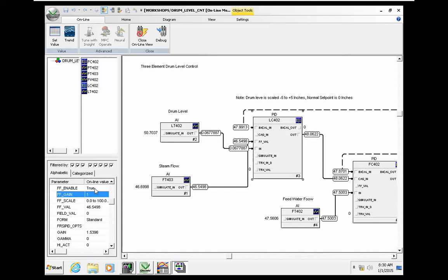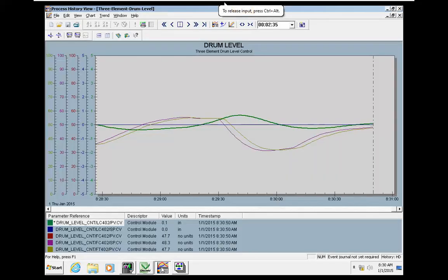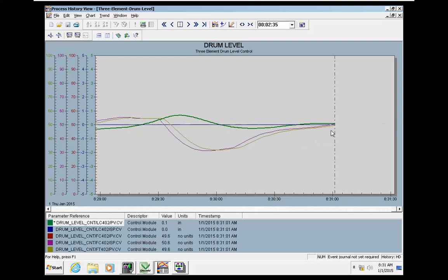in PID1, we are making it steadier. You can see that the level control is getting more stable, with fewer variations in the level control. It's a great tool. It's also possible to implement the same behavior by MPC.